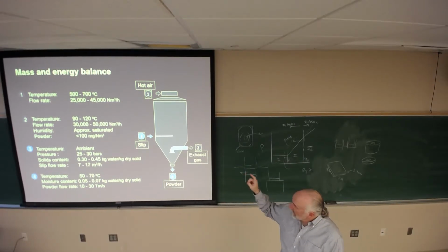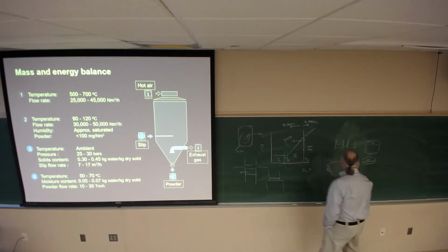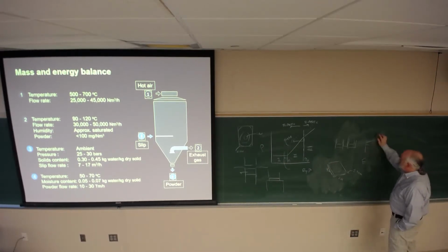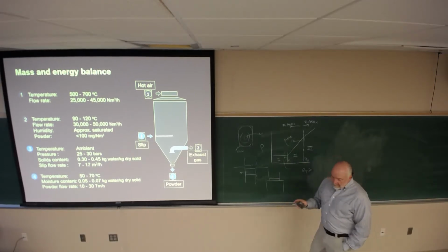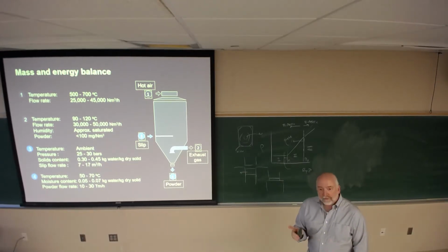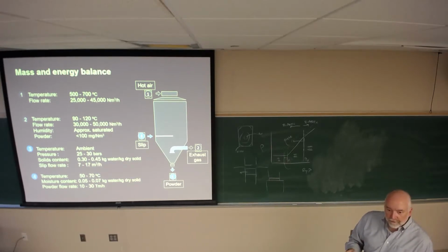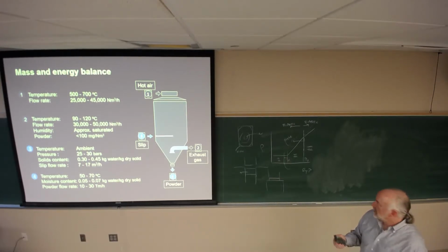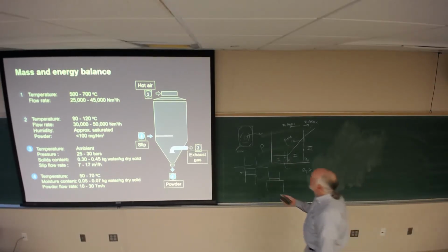Okay. And in China, they don't do that. They bring in the raw materials and they get ground on site. And in that process of grinding, they are also mixing. So they have large continuous ball mills, okay, that take that material in, typically in the slurry form. So there's another benefit of spray drying, and that benefit is that by slurry forming, you get better mixing. So the uniformity of the tile is better microstructurally and compositionally. So that material comes in and gets spray dried, and that provides flow that they need for uniform compaction behavior and die fill, and that costs a huge amount of energy to do that.